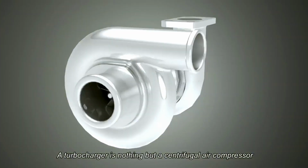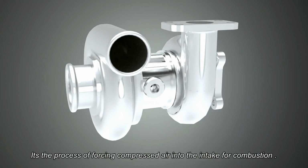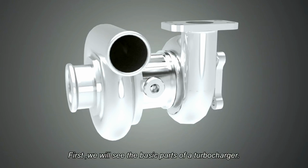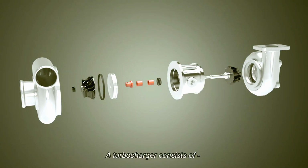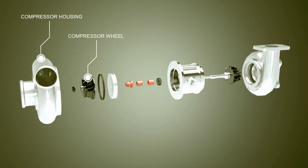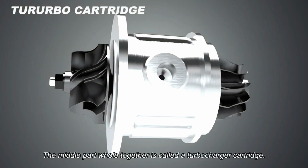A turbocharger is nothing but a centrifugal compressor. The principle here is forced induction. It's the process of forcing compressed air into the intake for combustion. First, we will see the basic parts of a turbocharger. A turbocharger consists of a compressor housing, compressor wheel, turbine housing, connecting shaft, bearings, and oil seals. The middle part held together is called a cartridge.